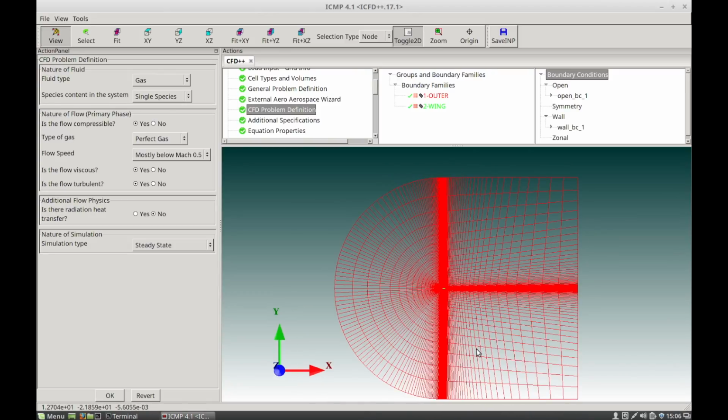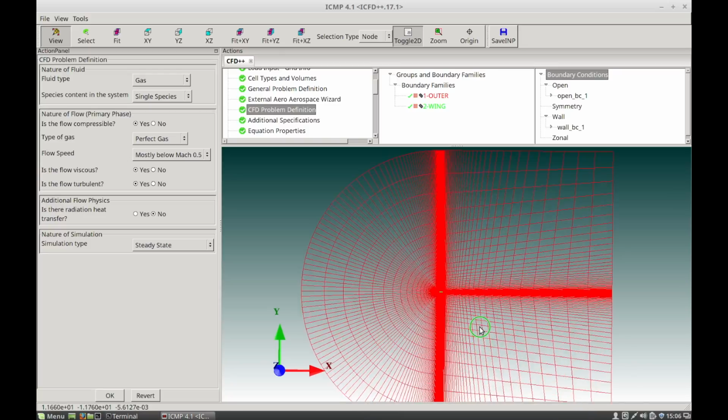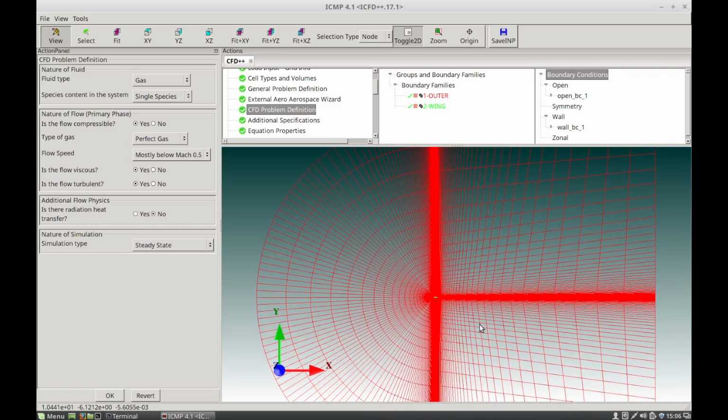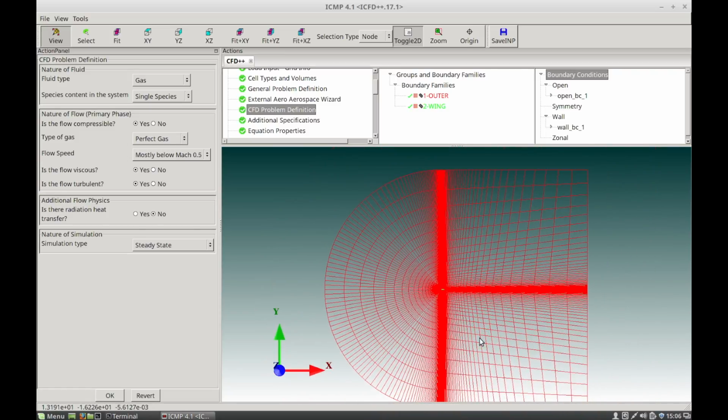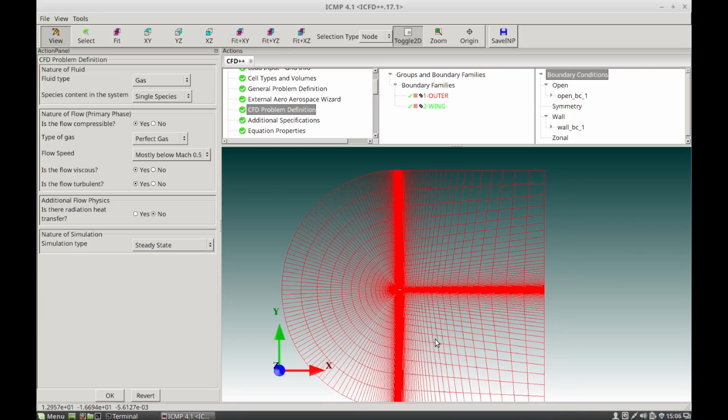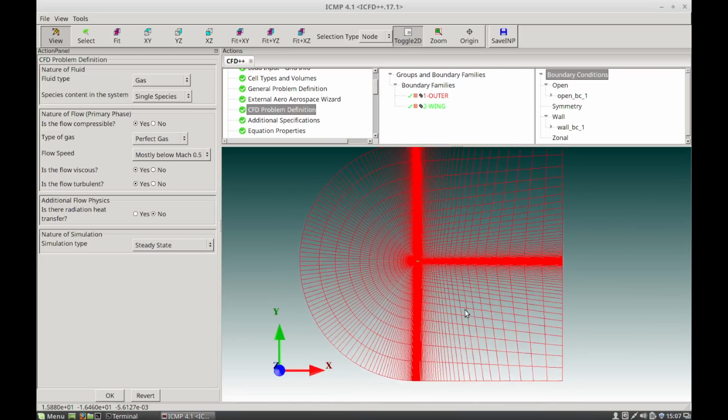You can zoom the view by also holding down the right mouse button, but by moving the mouse up or down. The up motion zooms in, and the down motion zooms out. Finally, the geometry can be translated or panned across the screen by holding down the middle mouse button and moving the mouse in the direction you wish to move the geometry.